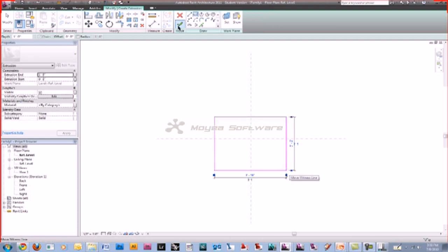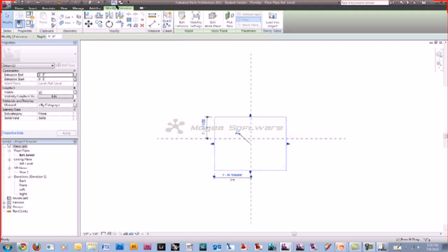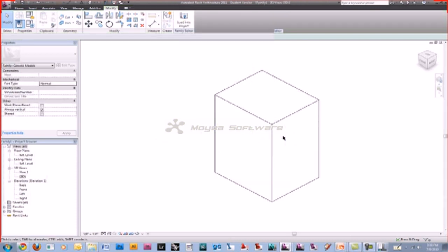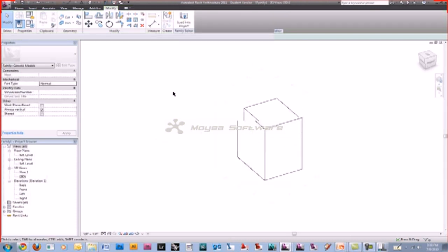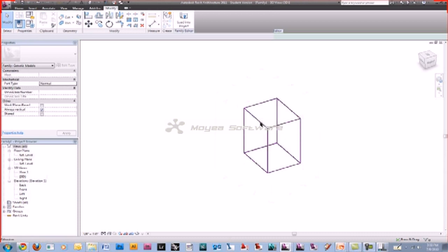Revit operates off families, period, but this is where you would go if you need to make a one-off product for a model. Say you're making a residential home, and the whole home is based around a repeated unit. You could come into a family mode and actually create a family, and that family could be placed anywhere inside of the modeling world. And of course you have that parametric side as well, where you can create parameters to adjust the size and shape of that element, which is a little more advanced, but we'll get into that as well.